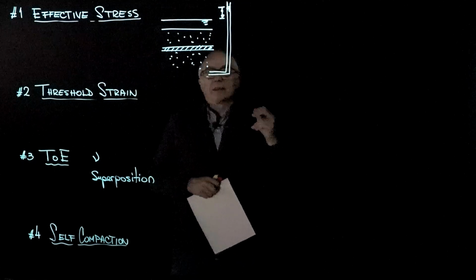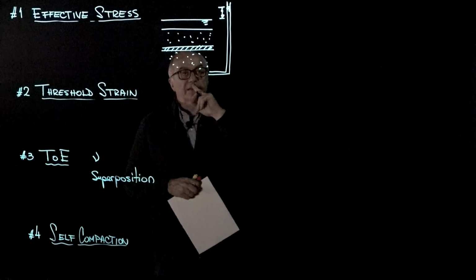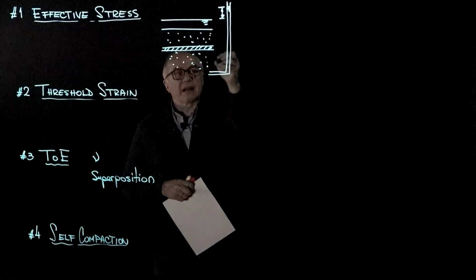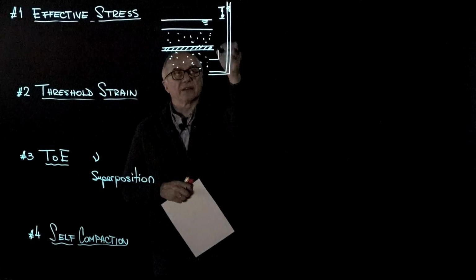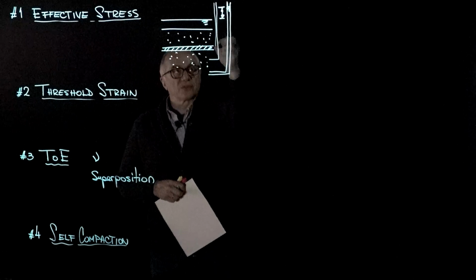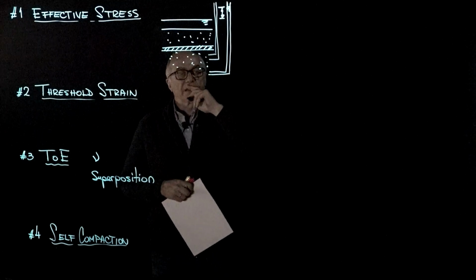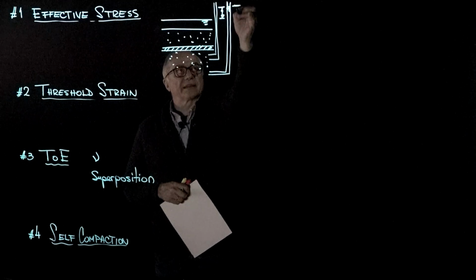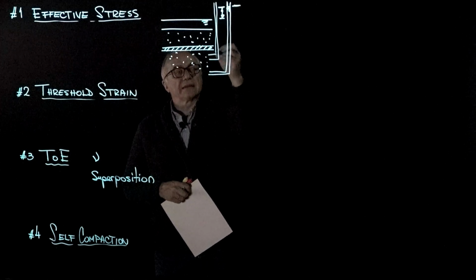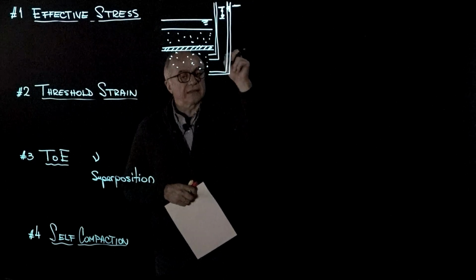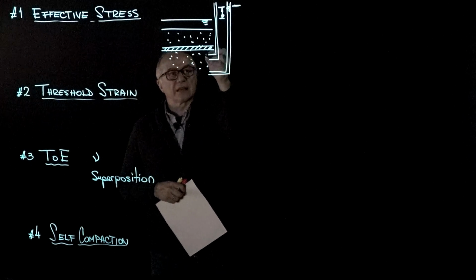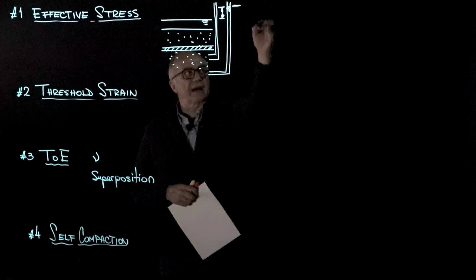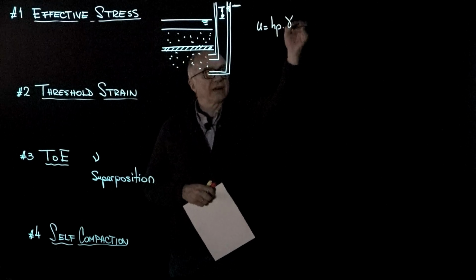And so the first thing that we ought to recognize is that because this is a hydrostatic system, wherever I place a piezometer here, it will rise to the same elevation. Therefore, if this is the height of the piezometric head, then I can immediately tell the pore fluid pressure at every point, which is the piezometric height times gamma water.